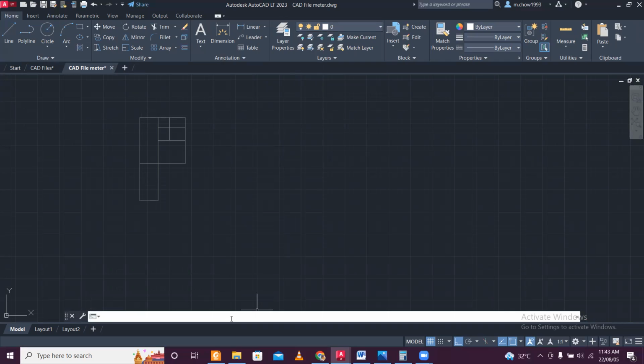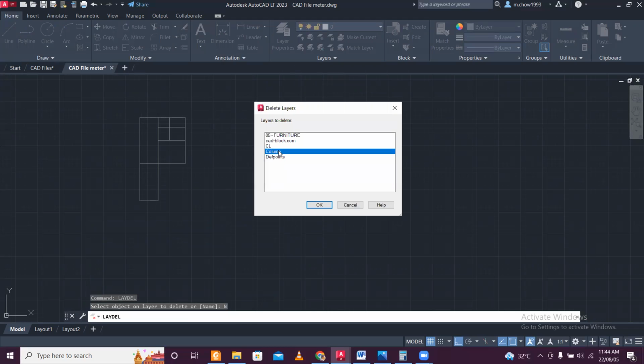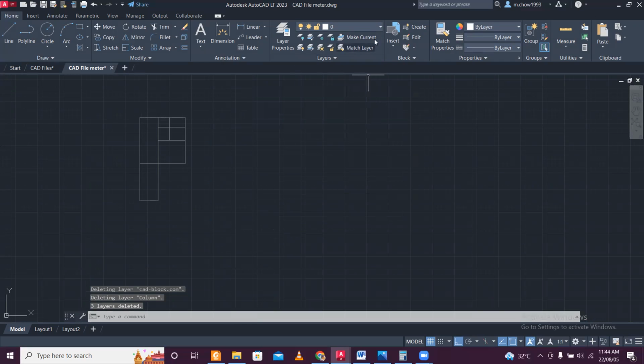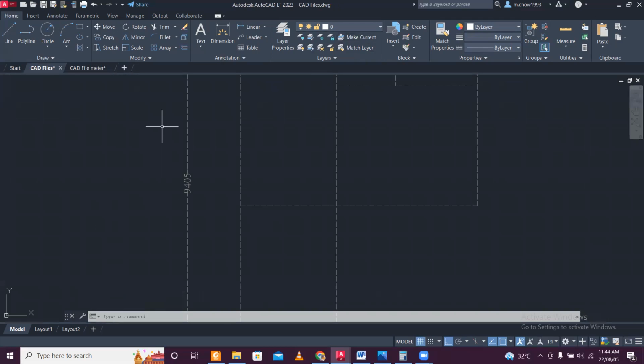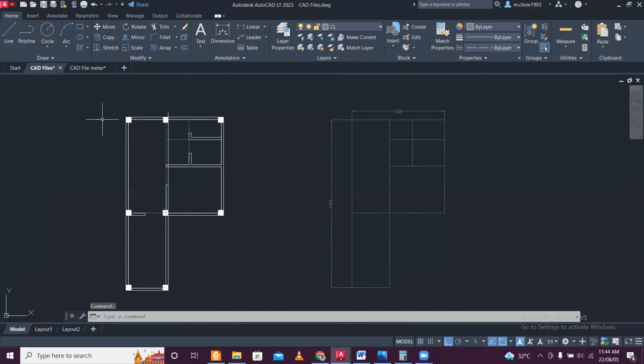And here all the other layers except the center line we'll delete, because we don't want STAAD to get confused by unnecessary things. So L and click on enter, and name, and column we'll delete. Depth points we'll keep because this is a default thing. Okay, and now we can see only these three layers are there, and for the column positioning we'll just use this file for the column position.